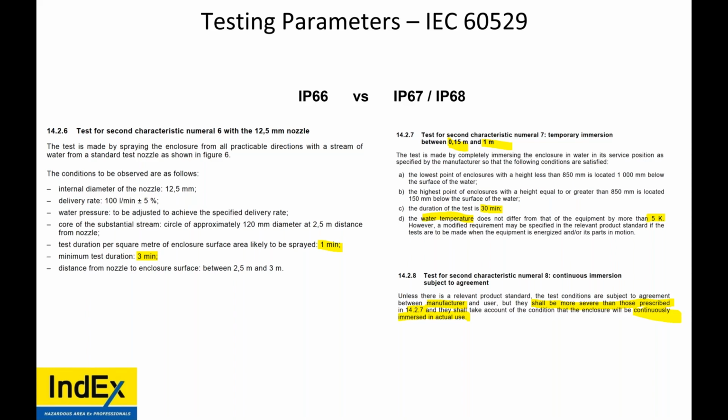That water vapor is going to turn into a liquid. So why are you going to keep finding water inside your boxes? Because you don't have a breather near the top side of your box. Some enclosures, important ones like control panels, have 2 breather drains installed. When it's installed at the bottom, it makes a very good drain. When it's installed near the top, it makes for a very good breather.